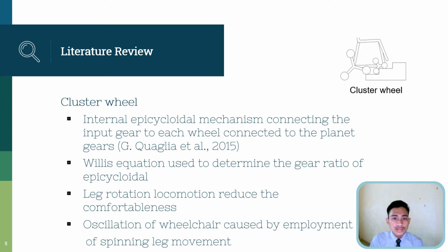However, they also state that using this rotating leg locomotion can reduce the user's comfort when climbing the stair wheel structure. The oscillation of the wheelchair is caused by the employment of a spinning leg movement, as the locomotion unit's center follows a cycloid-like trajectory during the steady state step climbing.